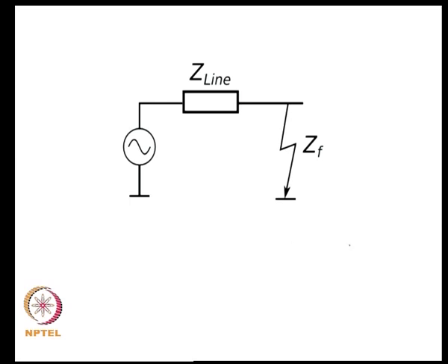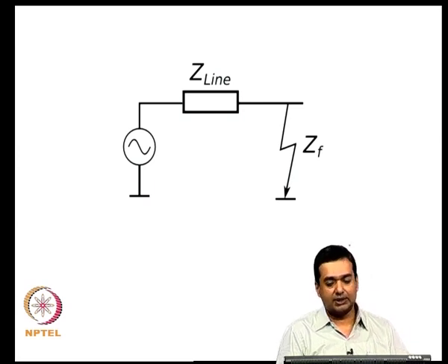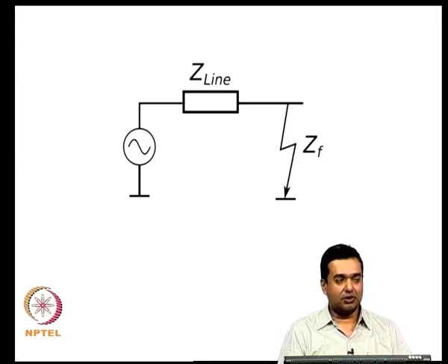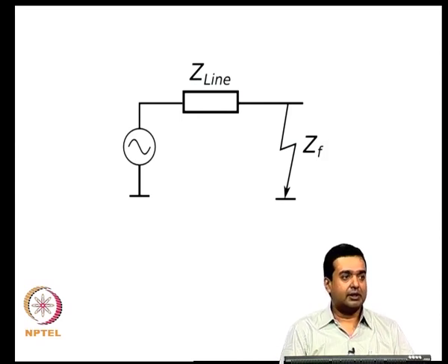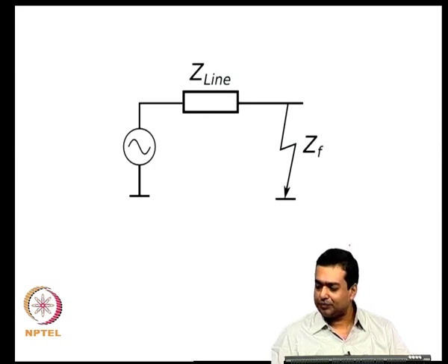If you have an overcurrent of at least twice the rated value for the given section, then potentially protective devices can start operating. So, you are talking about fault impedances starting from a dead short corresponding to ZF equal to 0 to larger values of ZF, but it has to be a small value of ZF compared to 1 to have the appropriate level of current, so that you could actually initiate protective devices.